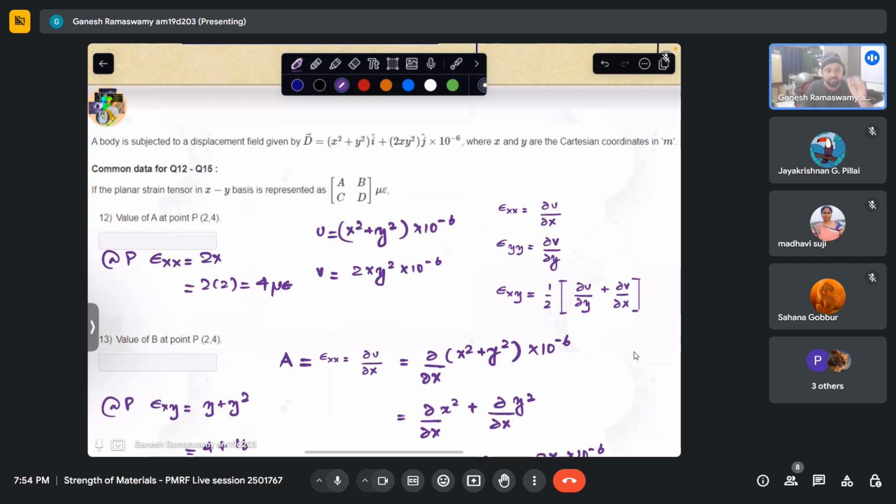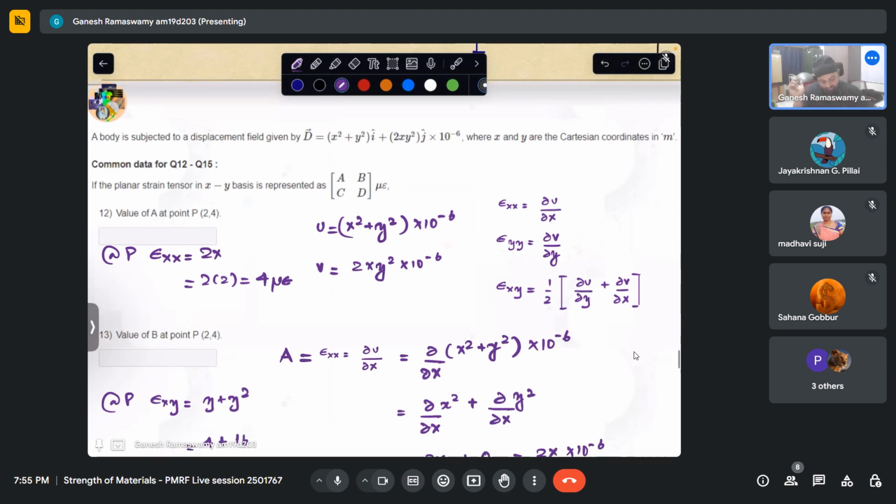Once we have sufficiently understood how this is dealt with point by point, then we will go on to dealing with the normal components that we come across in daily life, that is generally followed in the strength of materials course, that is beams, shafts and columns and so on. All those will also come, but presently we are focusing our attention at a point. What is happening at a point? How to write the stress tensor, strain tensor at that point, how to get strains from a given displacement field, and so on. So this is how we will calculate the strain tensor.